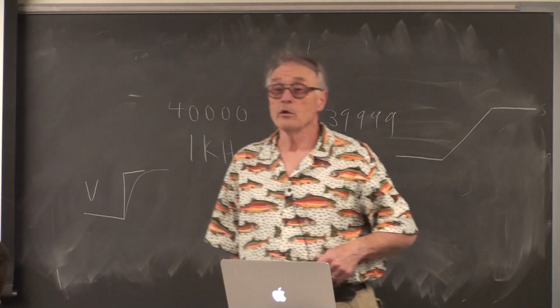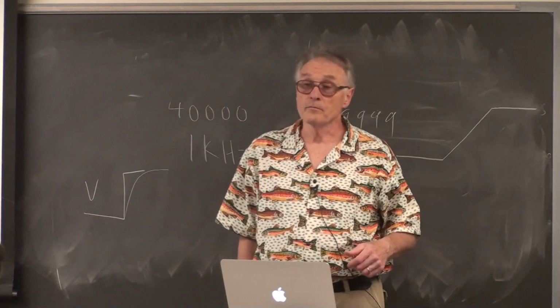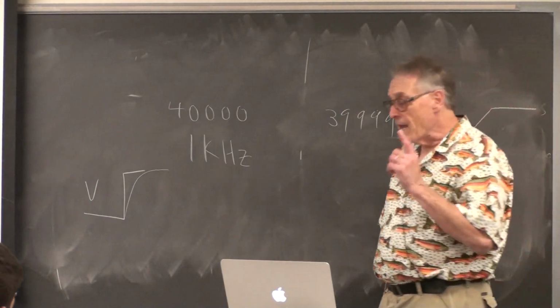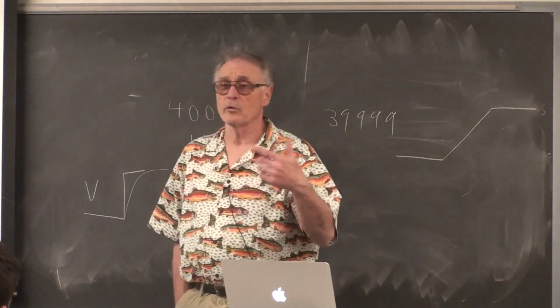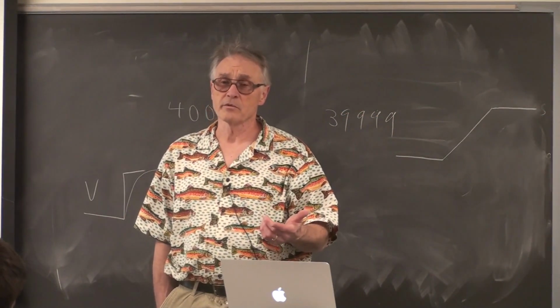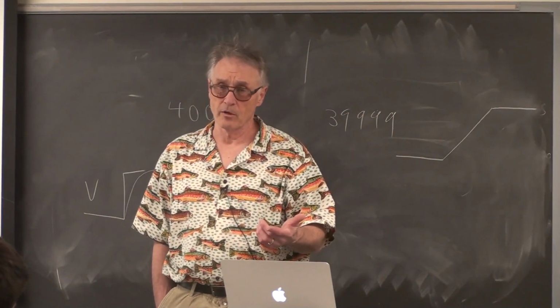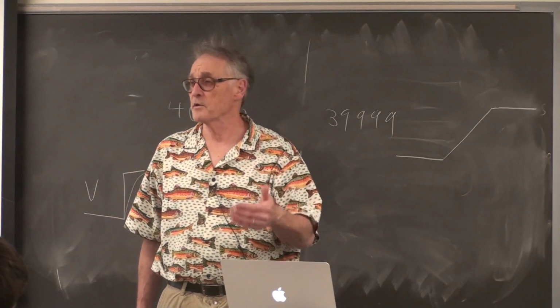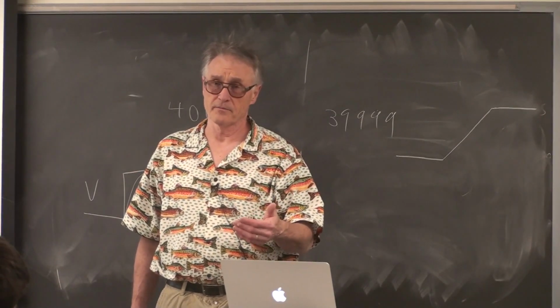Oh, sure. Before the ISR, inside the ISR, outside the ISR, just calculate the whole in, during, and out. You can't read it outside the ISR because you don't know when the ISR happened outside. And since it's asynchronous with respect to the main program code, you can only read the timer inside the interrupt service routine to get interrupt service routine related things.